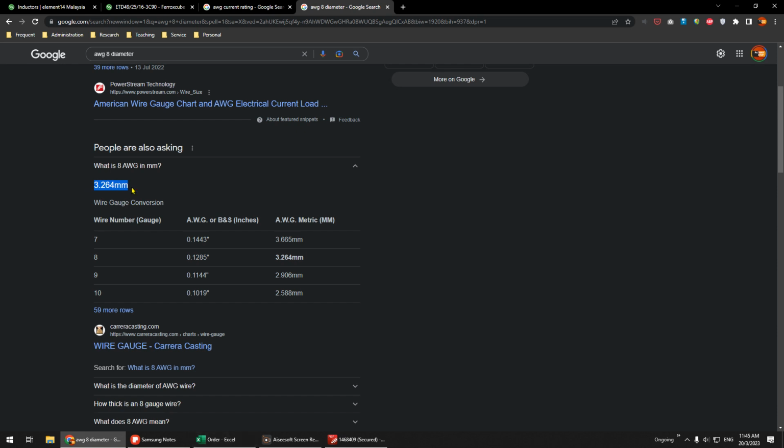The problem is the wire is quite thick, so it's quite hard to wind. To avoid this problem, usually the thickest wire we use is 1.5 millimeter. 1.5 is also quite difficult to wind, so I suggest maybe 1. Not 1 AWG, 1 mm wire. You choose 1 mm wire.